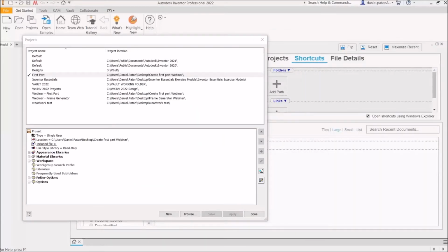It won't go up onto my desktop unless it really cannot find that part. Then it will start to look through folders above it, but you don't want Inventor to start doing that. Otherwise you'll start to see performance issues and then it ends up selecting the wrong part and it just becomes chaotic. So you want to make sure that you've set the project file, and then going forward, anytime you save a part, it's going to be saved into that folder.